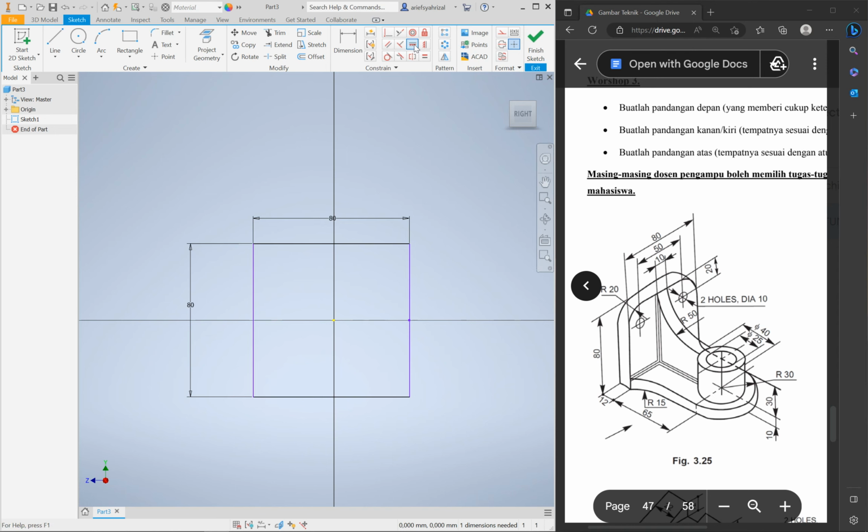Then switch to the horizontal constraint and select the center part, and it will automatically turn into black lines, which means your sketch is constrained. It will be okay for the rest of the design.